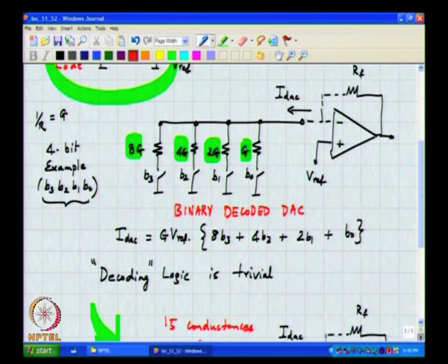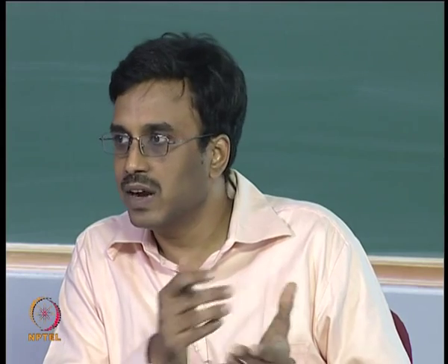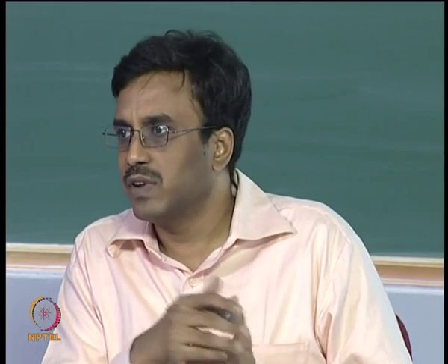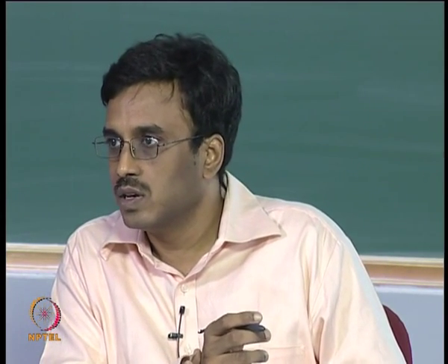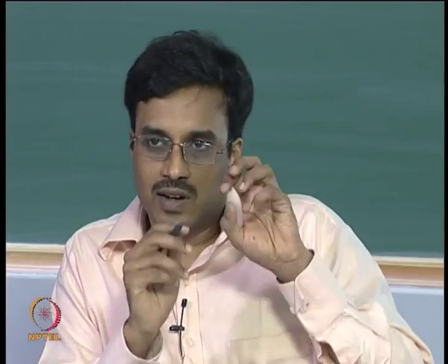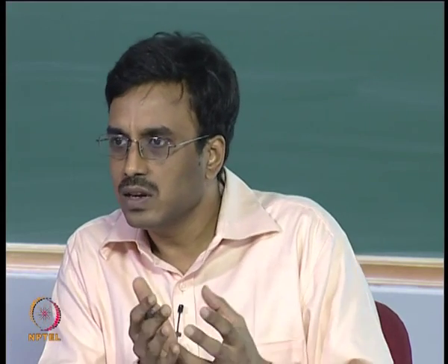Is this clear? Now, what he points out is a very valid and relevant point. We all know that none of these elements will be, within quotes, exactly identical or exactly the right multiple of G that we want. They will deviate from each other due to manufacturing tolerances. And by the way, how do you expect to get 8G? If you want to get 8 times the conductance, what do you think you will do? Take 8 conductances of G and put them in parallel.